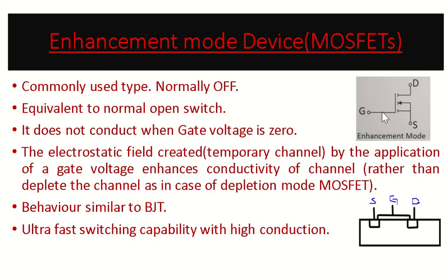So unless and until we apply voltage to this gate terminal, the channel won't be completed, because as I told, it's in a normally off state, right? Unless and until we provide some voltage at the gate terminal, the MOSFET will not turn on. Okay, so that is one key point which you have to remember.